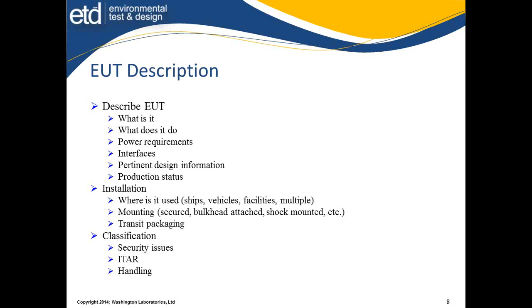Does that mean the rack is shock mounted and you should do your test in a shock mounted rack? Well, if you do, then you have to decide how you are going to manage the shock mounting weight ratio. If I've got a full rack that weighs 400 pounds and my piece is 40, I need the shock mounts to be proportional to the weight that's actually in test. So the evaluation has some merit.